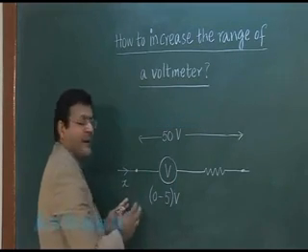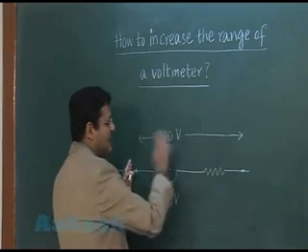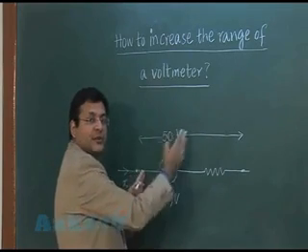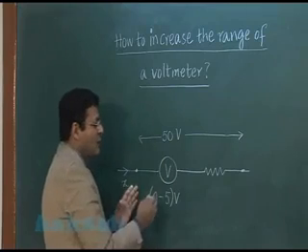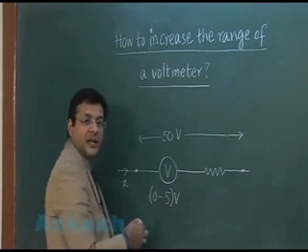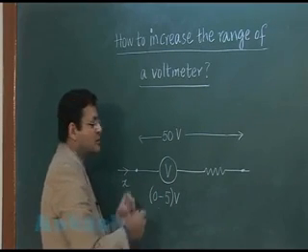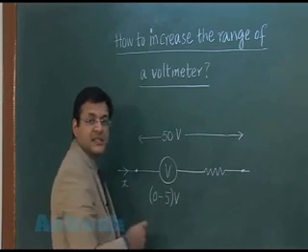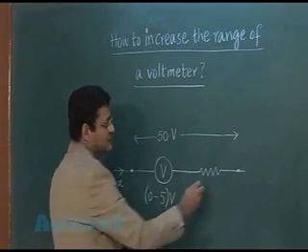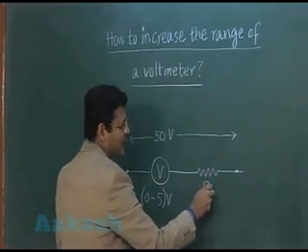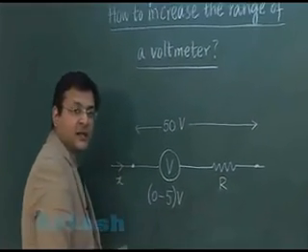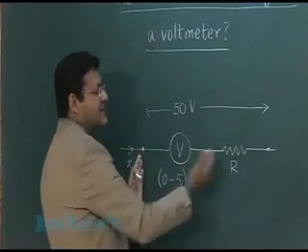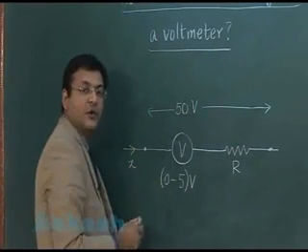But now my requirement is that voltmeter box, this is the entire voltmeter box now, it should measure up to 50 volt. अब वो 5 नहीं 50 volt measure करेगा. That will be possible only when आप इसका रेजिस्टेंस इंक्रीज कर देंगे. हमने इसकी सीरीज में let us suppose एक रेजिस्टेंस R कनेक्ट कर दिया, so that now the current multiplied by the entire resistance becomes 50 volt.